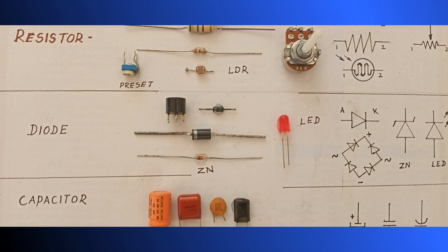On the top you see a black cylindrical part with 4 leads. That is 4 diodes encapsulated in a small cylindrical form, which is called the bridge rectifier. Next to that, a small diode you see, that is a 1 ampere diode, a normal diode, and below that you see a little bigger diode, which has more power, a 3 ampere diode.